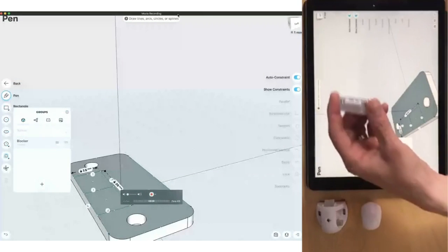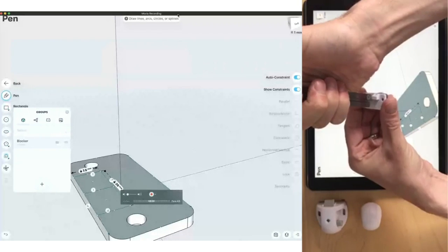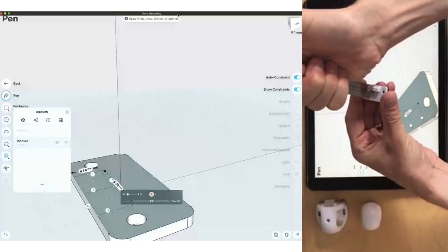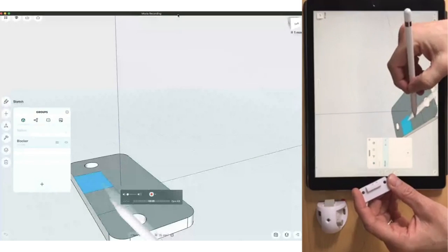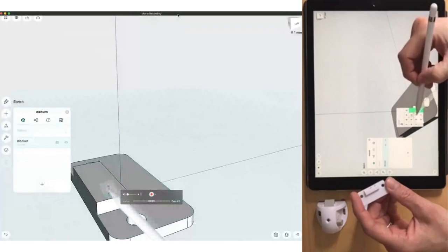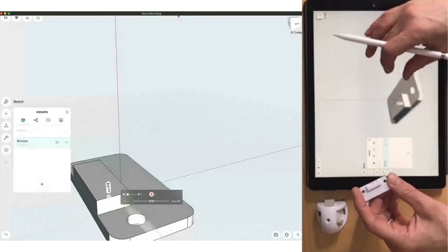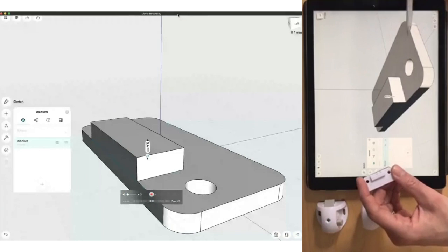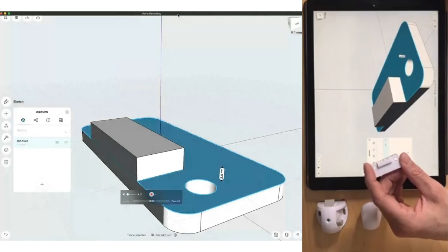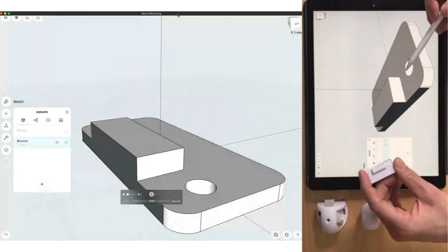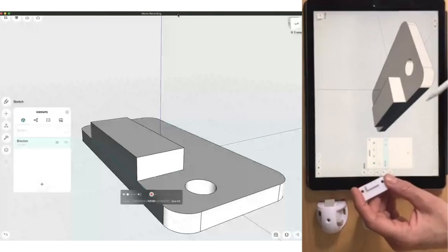Okay, so how deep? Well, let's measure. That whole thing goes, what, 3.5 millimeters? Yeah. Yep, 3.4. So I select these two cubes, drag up 3.4. And because I'm extruding this from a sketch that is on the face of this first object, the object is actually joined. So we add it to it. Pretty cool.